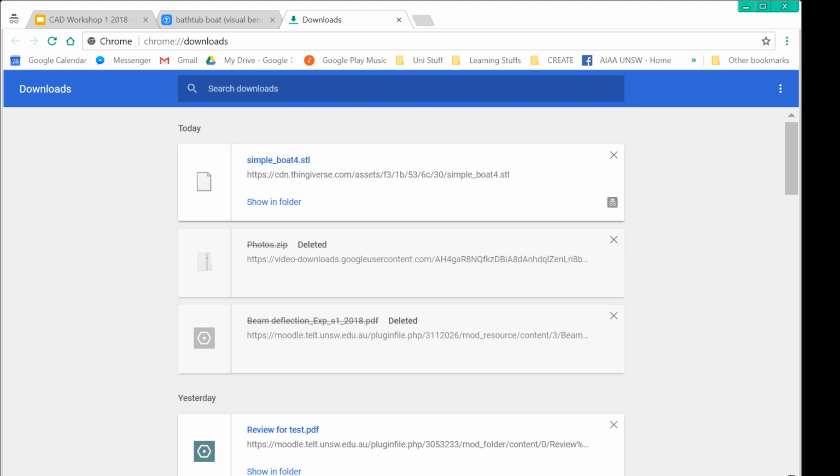There is a way to convert this, if I remember. If you go to model, there we go. You want to convert that from a mesh to a B-rep. B-rep is actually editable. A mesh contains a large number of facets, so that's why I said complex shapes make it a bit difficult. No reason to mess around with STLs, but it's a fun little skill if you do want to learn. But yeah, that's pretty much it.